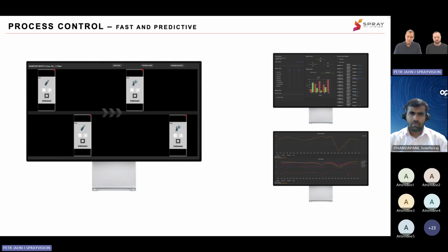Once you are using cabins where there are more robots, you are able to very easily create a model of the cabin with the different applicators. Once you collect it on the skid, you just take the samples, place them in the unit, and click on the specific robot, and the software gives you a green or red light if there is an OK pattern and you can continue production. Or if there is some issue, you just need to click on the high level of detail, understand what the source of the defect is, fix it, and then you can continue mass production again.